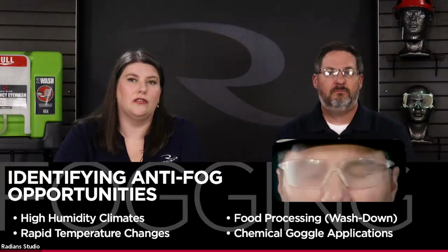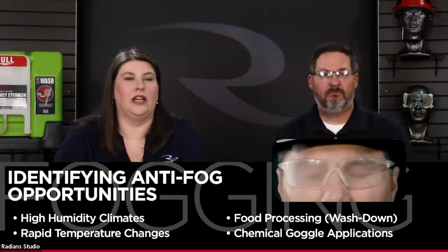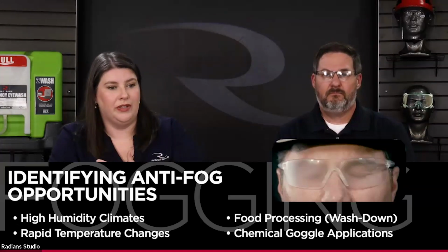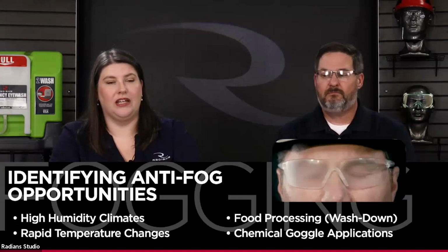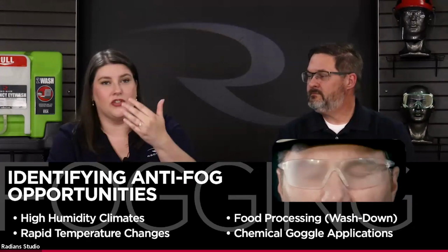And so you want to make sure that you're looking. When we look at these scenarios, there are common things that come up all the time, and one of them is that goggles or face shields fog really easily. That's right. So anytime you're employing a goggle as a PPE device, you're likely in one of these scenarios with potential for fogging: high humidity climates, rapid temperature changes, like going from a cool building to outdoors, or from regular indoor temperature into a freezer or refrigerator.